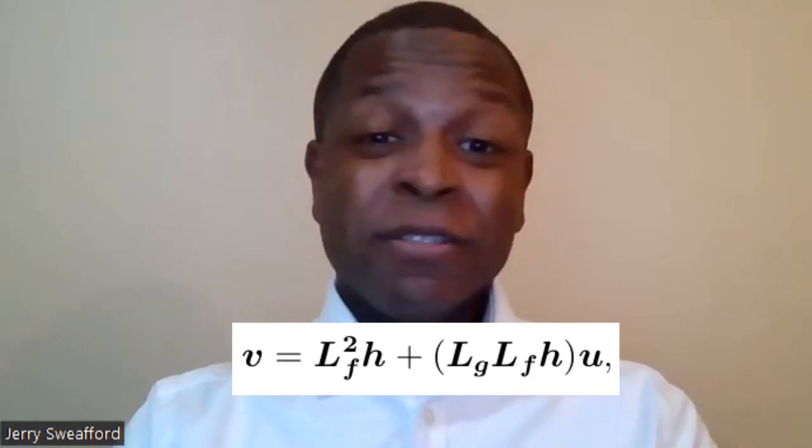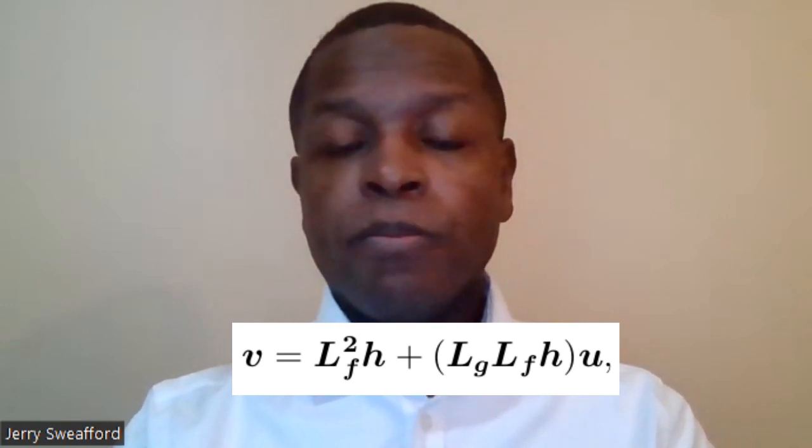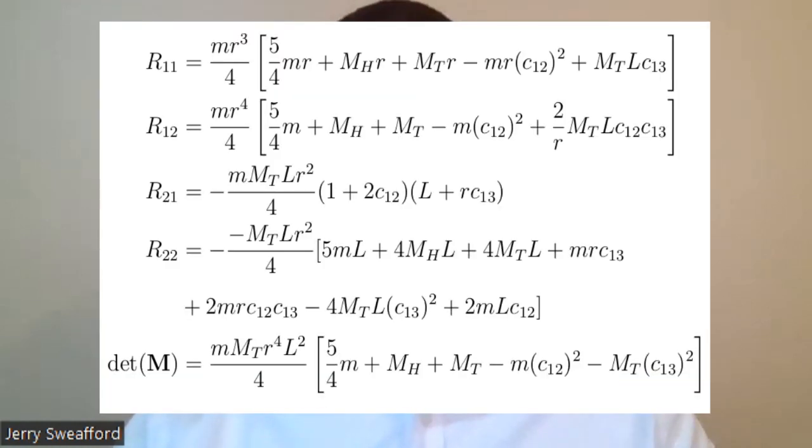Feedback linearization is a simple way to derive a controller that can drive outputs to 0. If we have defined our outputs properly, then driving the output vector y to 0 will result in desired walking behavior for the robot. Let v be a secondary control that is equal to the second time derivative of y. That is, y double dot equals v. We can also define v in terms of Lie derivatives and our primary control u. Here are the substitutions used in this definition of v.